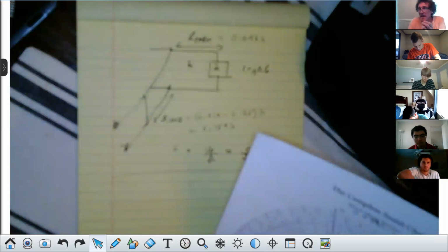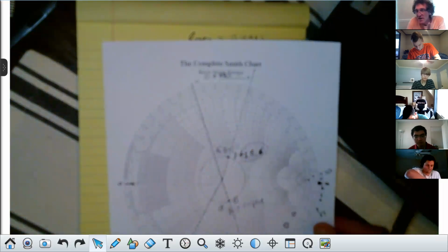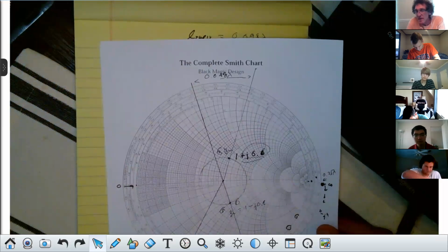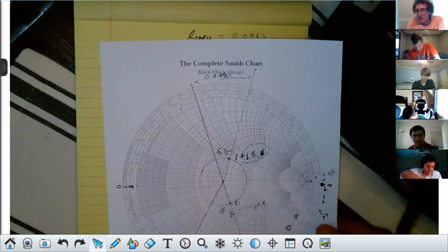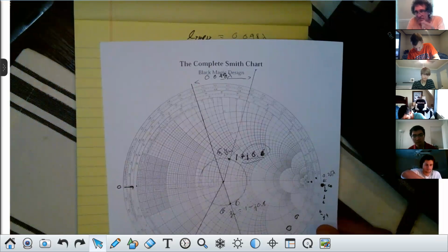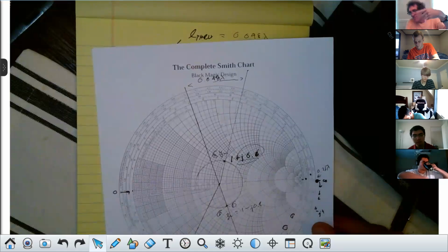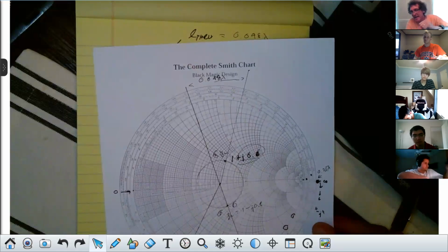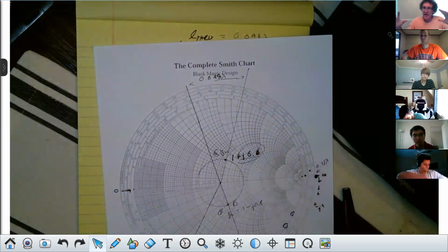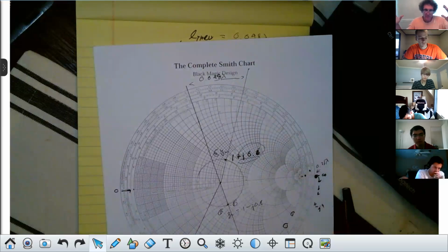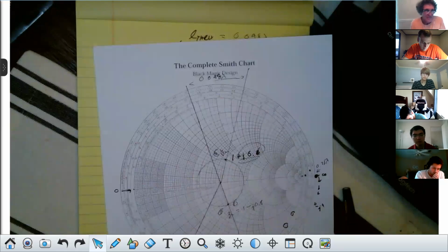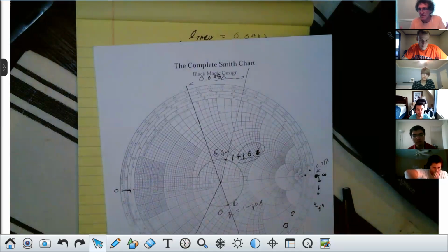And one last thing, in general, we shun using inductors, right? And there's a primary reason for it. Generally, when you've got current running through an inductor, it has a magnetic field around it, and the magnetic and electric field caused by the time varying magnetic field will influence other electronic components. Inductors are by nature evil in terms of their electromagnetic interference. It causes a lot of problems with interference.